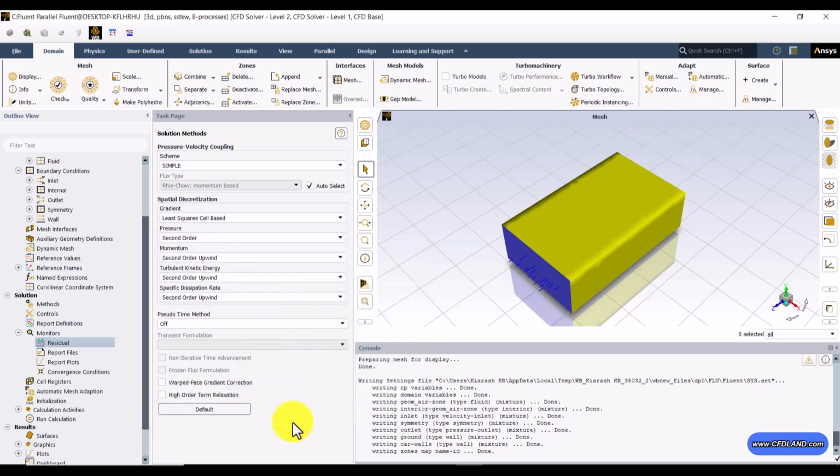So how can we guarantee a convergence, and how can we make sure that we have reached the convergence? For this purpose, the main option is to monitor a specific, sensitive, and even important parameter during the calculation. So as soon as it reaches a constant value, we can be assured of our convergence. So you may ask where to put it.